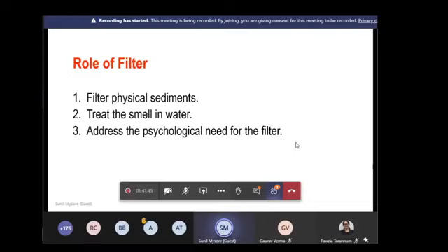Now, I will not get into all this COD BOD talk at this point because it is totally irrelevant so far as rainwater is concerned. I just put this point here because there's a lot of technical discussion and many questions asked about COD BOD when it comes to rainwater. It is totally irrelevant. We don't even need to mention these terms, because they don't relate to rainwater at all. So if somebody is telling you we need the filter to take care of COD or BOD, no. Rainwater doesn't have any of this, so we really don't have to bother, unless you're going to have some kind of mixture out there. COD, BOD is irrelevant as far as rainwater is concerned.